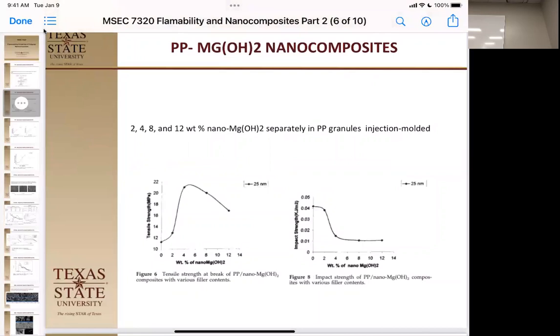Again, impact strength goes down. Why? It's becoming more brittle because there's more of a brittle material in your matrix, right? And actually, magnesium hydroxide platelets are almost like talc. They're very brittle. And so not only do you get a decrease in impact strength, but basically you're filling that cross-sectional area of resistance with things that aren't helping at all.